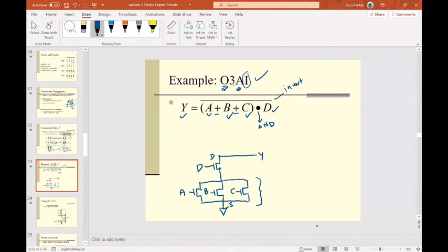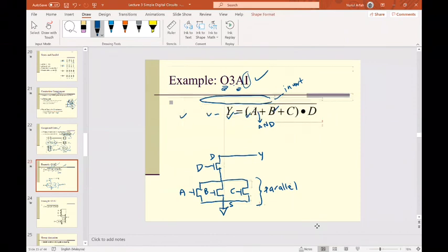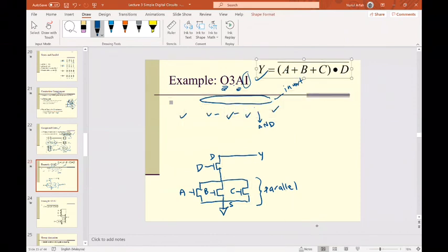And then the negate side, the invert. So what should you do? How to invert that? Since these are in parallel, the PMOS should be in series, right? So how to draw that? If you have a series, maybe I should make it smaller, or just move it here and erase everything.